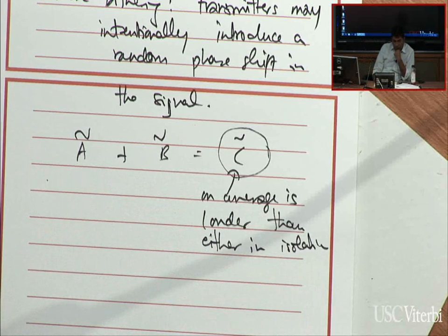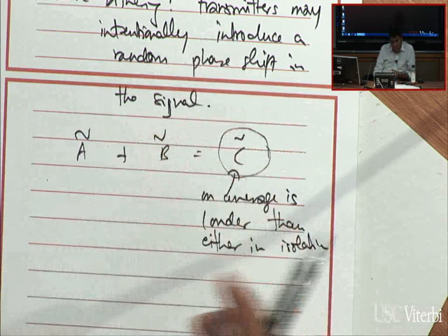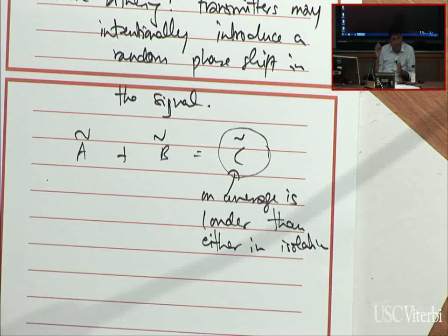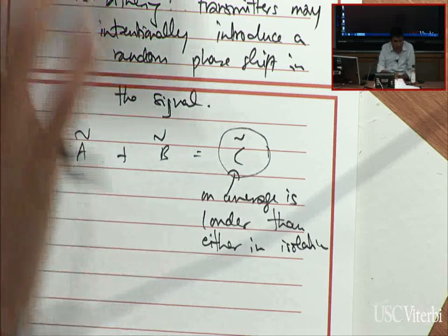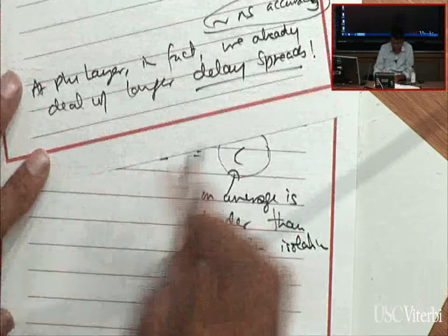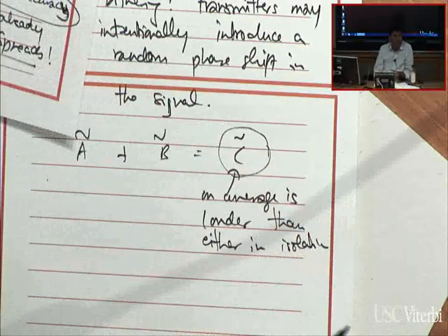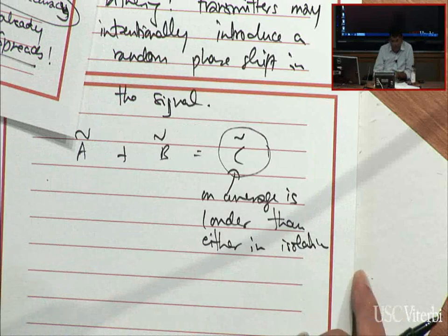And so in these systems, they are leveraging two sets of issues. One is to use phase dithering to prevent any worst case scenario from persisting forever. Like if these two nodes were always stuck in the worst spot, you actually are making things worse. So phase dithering handles that by adding randomization. And on the other hand, you use techniques for dealing with delay spread to handle other variations in the phase synchronization.